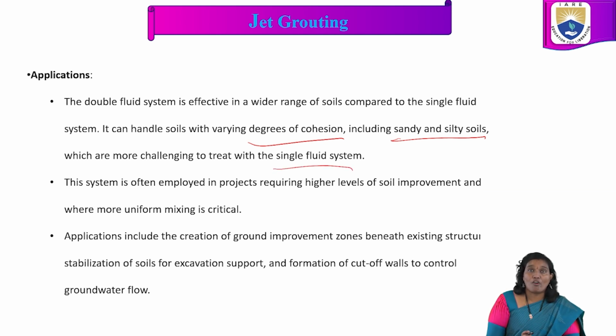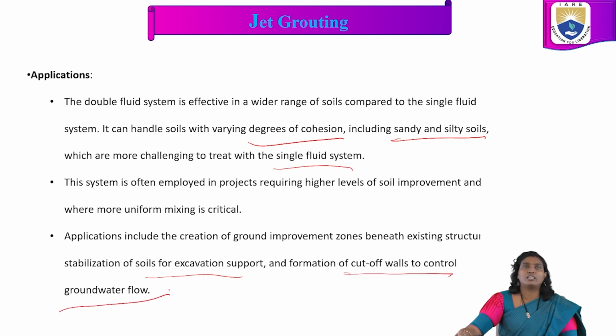This system is often employed in projects requiring higher levels of soil improvement and where more uniform mixing is critical. Applications include the creation of ground improvement zones beneath existing structures, stabilization of soils for excavation support, and formation of cut-off walls to control groundwater flow.